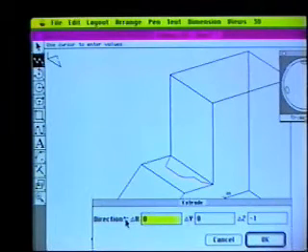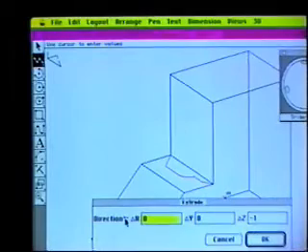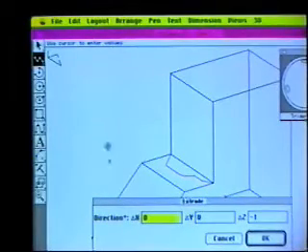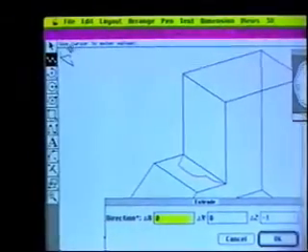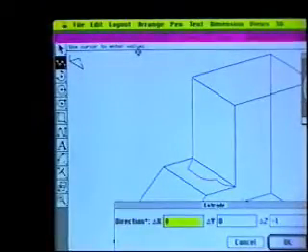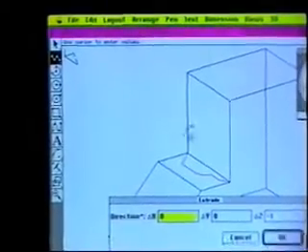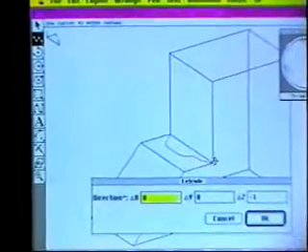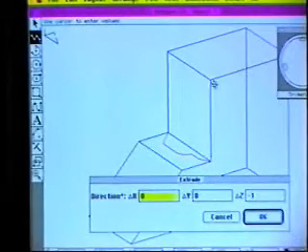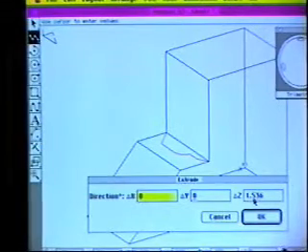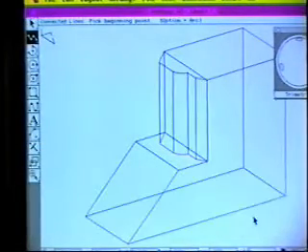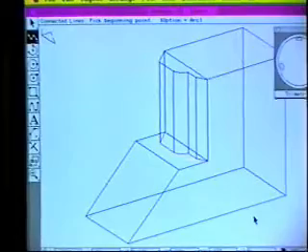But because of this asterisk, and this is something that occurs throughout Vellum, and I'm going to go up to the title bar here, it says use the cursor to enter the values. So all I know is that I want to extrude from here to here, and notice that it filled in 1.536, and when I say OK, then my extrusion happens automatically.